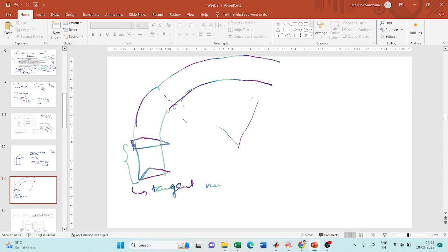Okay, then what do you think this will be? We already saw that from a straight section to a curved section, in most cases you should provide a transition curve between these two. And we saw the reasons: you should be able to introduce the radius smoothly.